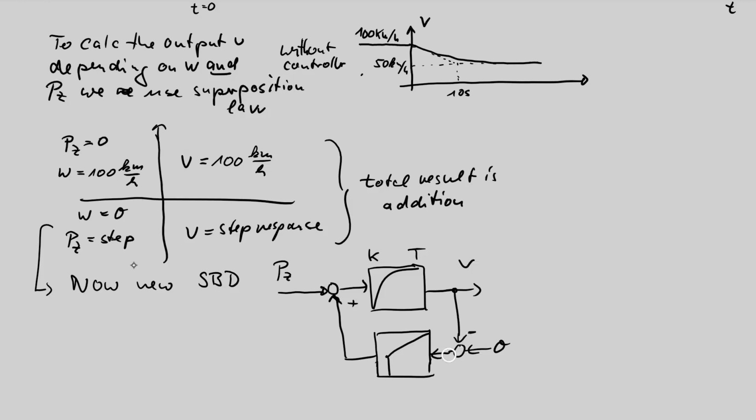You see this minus sign? It's just an inverter in this line, but it is unimportant if this inverter is at this position. A summing point with 0 input can be removed, and the minus sign can be shifted to that position so that we have a negative feedback.